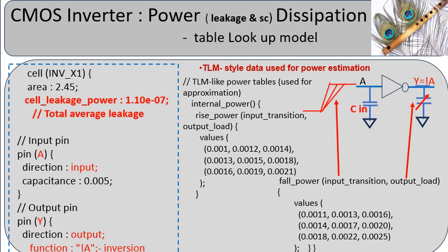As the dynamic power is dependent on several variable parameters like load capacitance, operating frequency, duty cycle, etc., it cannot be presented in the model, but depending on the operating conditions, is computed by the timing analysis tool.